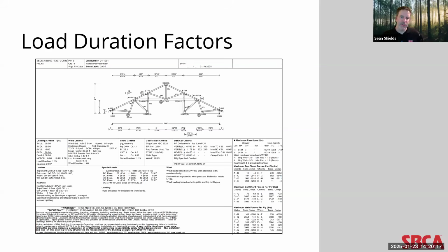So on the truss design drawing, the proprietary software will automatically apply the load duration factors once the truss designer selects the loading conditions. The software will then run through all the load combinations and apply the load duration factor associated with the shortest duration load in each combination required by the building code.